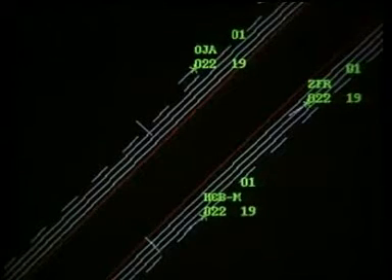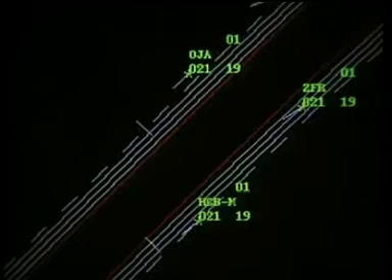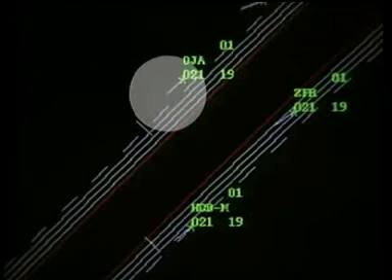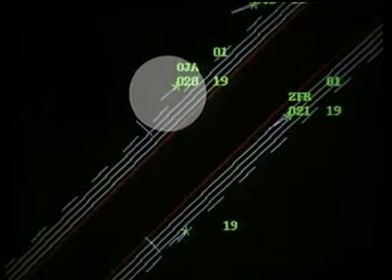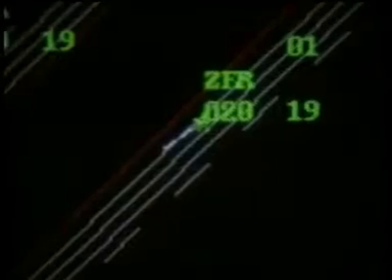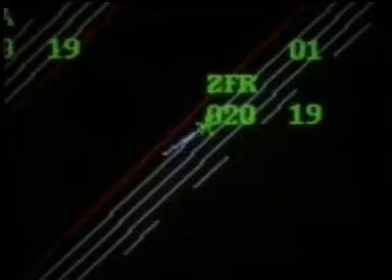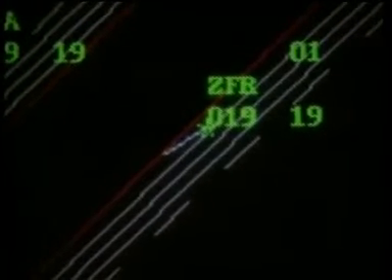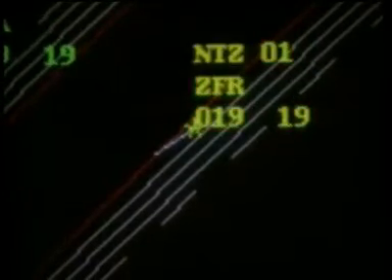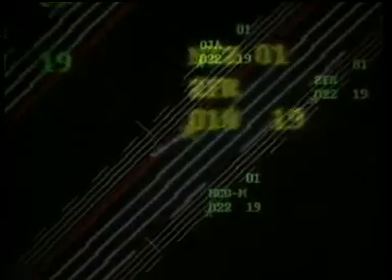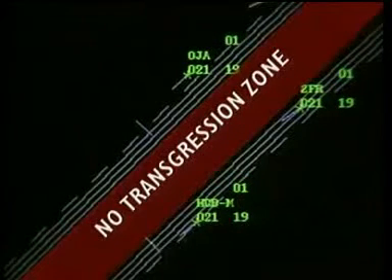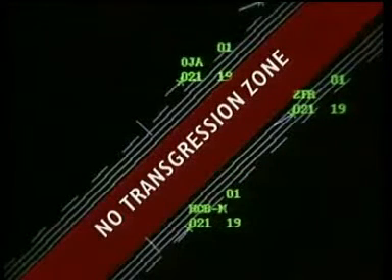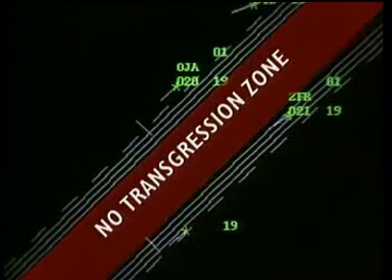The PRM controller uses a new radar display with a resolution far superior to existing equipment. The target update is faster than current approach radar systems. The radar has a predictor line that shows the predicted flight paths for the next 10 seconds, and computer-generated warnings assist in alerting the PRM controller when an aircraft strays from the approach course towards the NTZ. The NTZ, or no transgression zone, is depicted on the monitor controller's display. The NTZ is 610 metres wide.